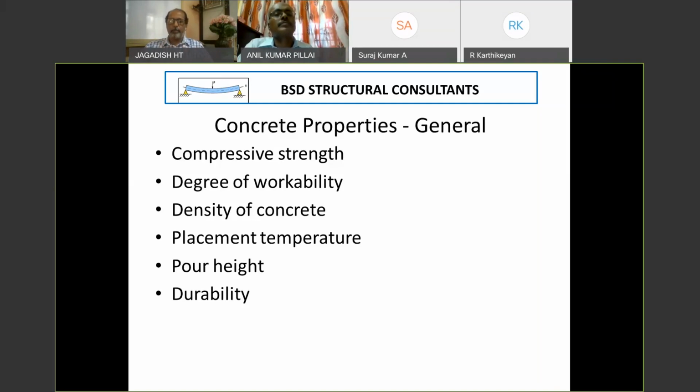So all the more important, the designers, when they're designing a structure, to keep in mind that the reinforcement, let us say if you take a column, the rings are kept in such a way that there is a place for inserting the tremie pipe. The diameter of pipe will be as big as even 5 inches to 6 inches. So we need to have a gap of that much for pipe to be placed inside and then for pouring concrete. So the reinforcement detailing should take care of this.